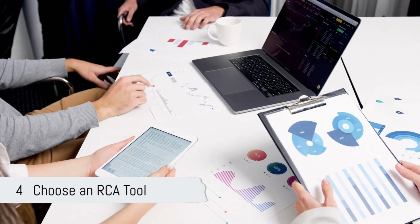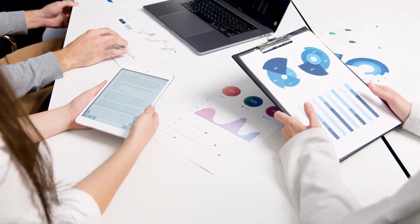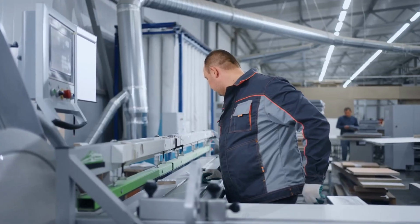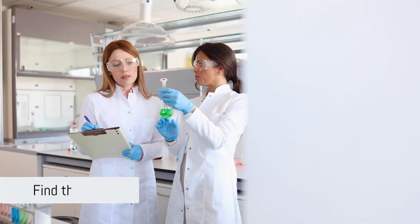4. Choose an effective RCA tool. Apply structured tools like the 5 Whys or Fishbone Diagram to identify potential causes. For example, if using the Fishbone Diagram, list out causes under categories like equipment, processes, and environment. Discuss each cause with your team to assess its validity.